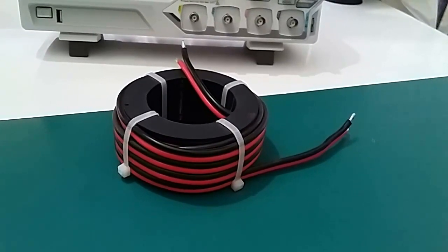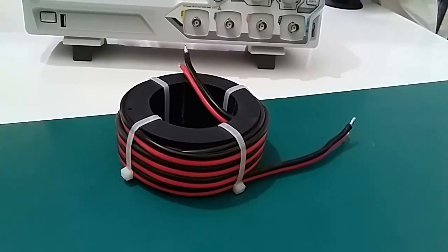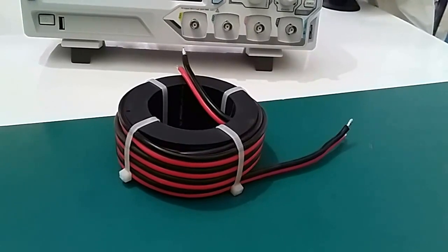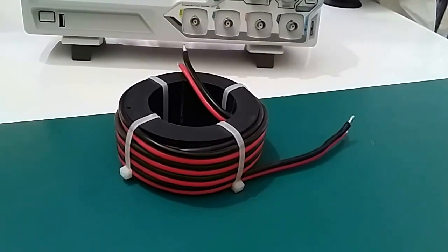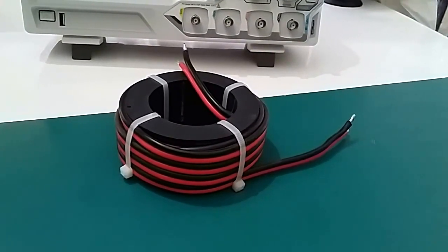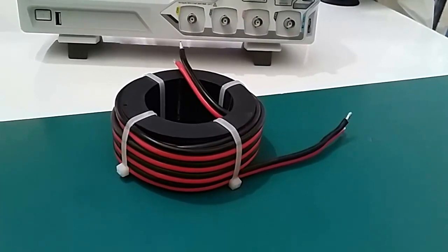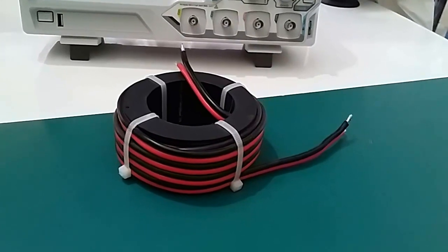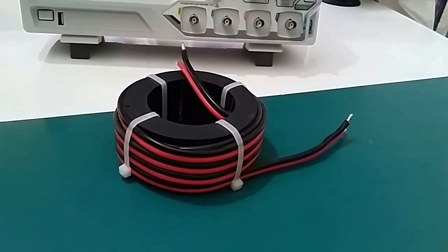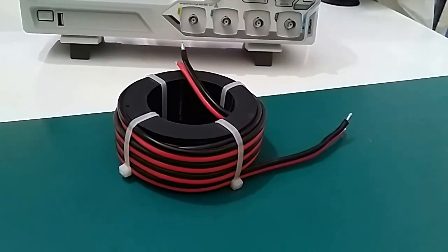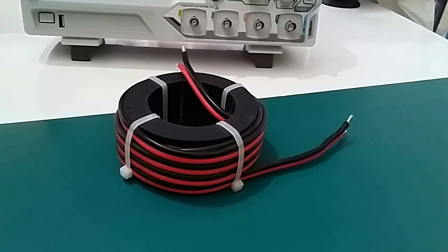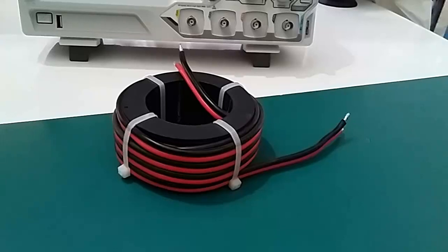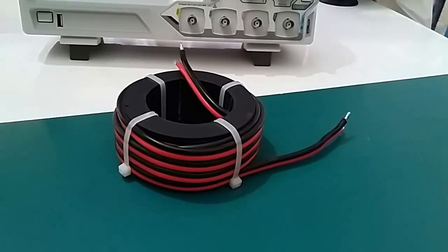Now remember, the goal is to get it going the opposite direction for the very, very simple reason that it's superposition. And obviously with superposition, if we can get the magnetic fields in the output coil to cancel, at least to a certain degree, then obviously the input is not affected so much, negatively at least anyway, by the secondary coil.